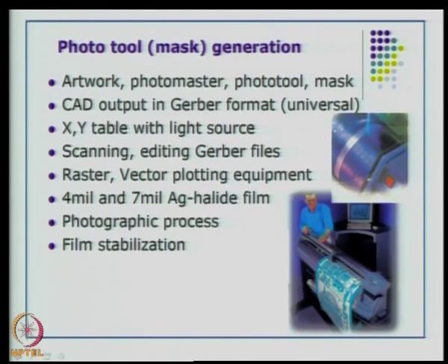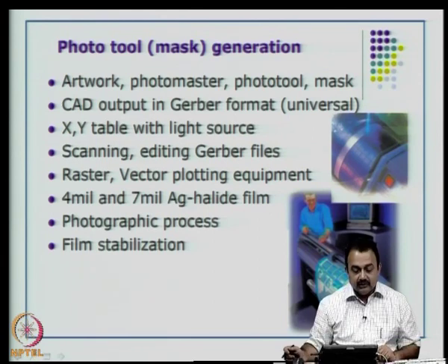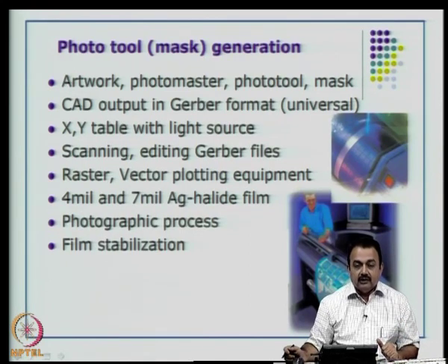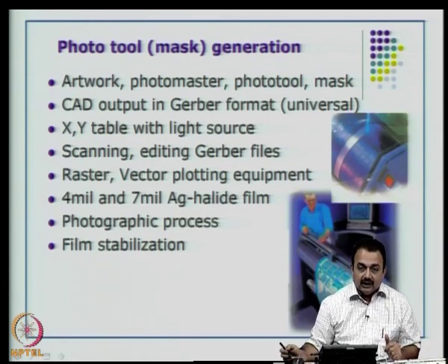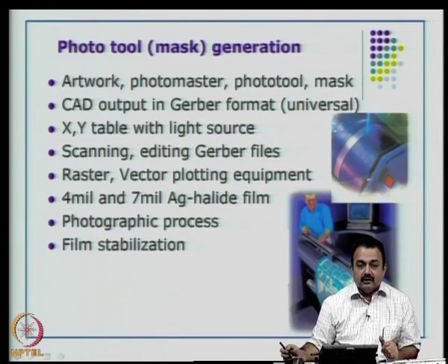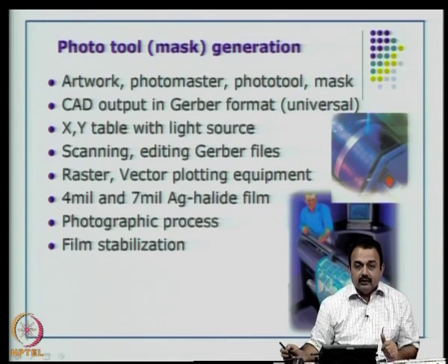Now, we talked about Gerber files. The Gerber files is actually sent to a place. If you have in your own institution a photoplotter, it can be fed to the photoplotter and you can create the mask. Otherwise, you have to look for a vendor who will create this photo tool or a mask and then give it to you, or sometimes the manufacturer has this photoplotter which will be in a clean room area,